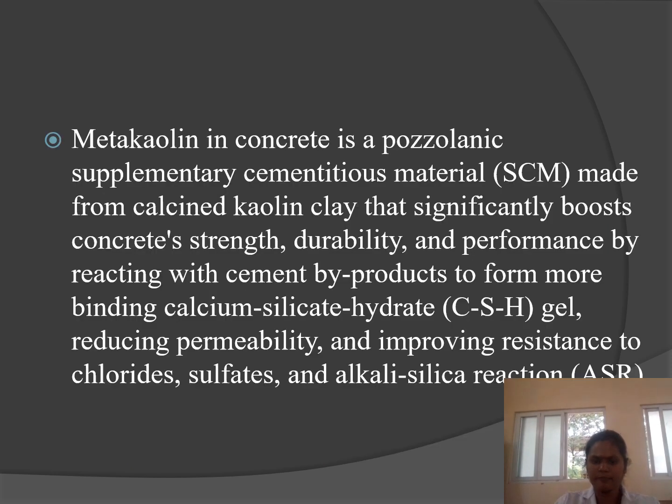Metakaolin is a pozzolanic supplementary cementitious material made from calcined kaolin clay, manufactured to boost concrete strength and durability performance by reacting with the cement byproduct to form more binding calcium silicate hydrate. It is called the CSH gel, where C means calcium, S means silicate, H means hydrate. It reduces permeability and improves resistance to chloride, sulfate and alkali reactions.